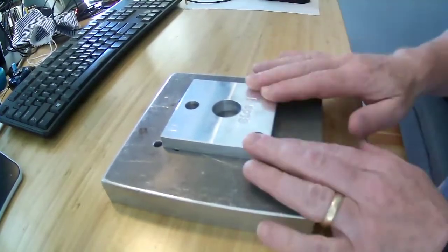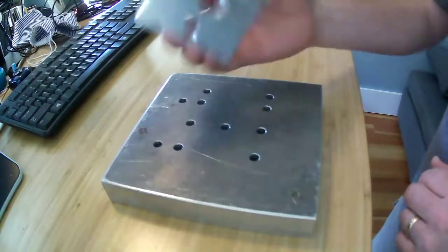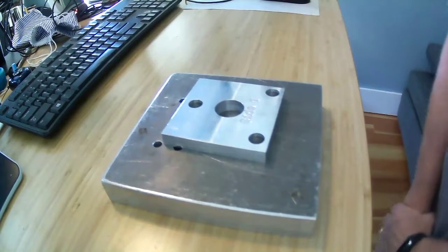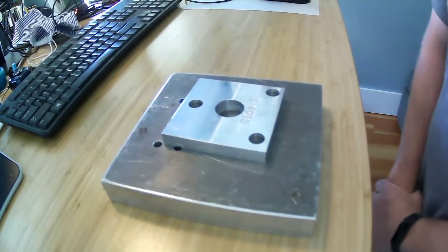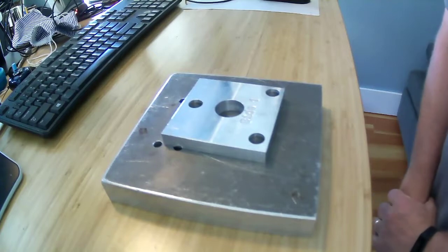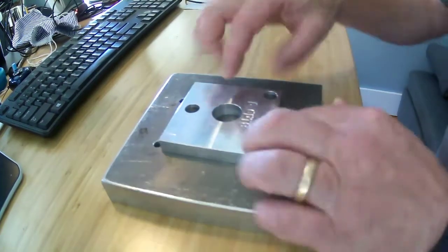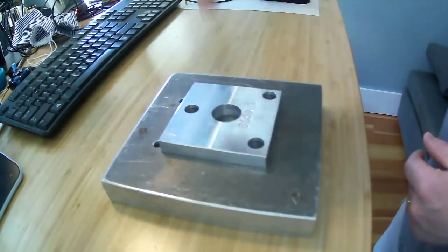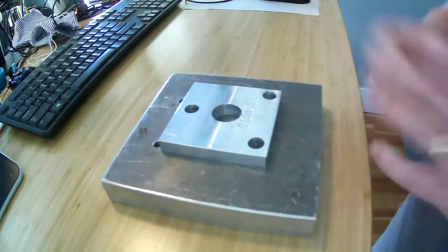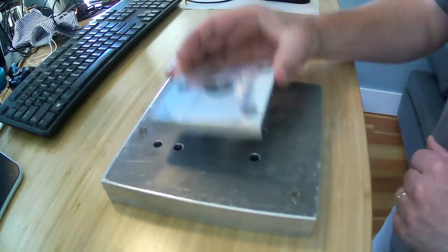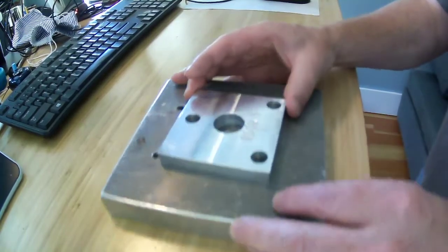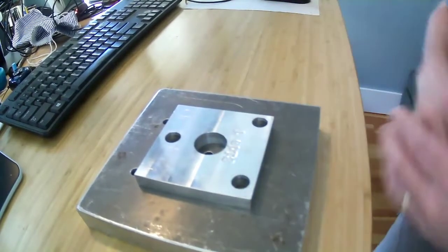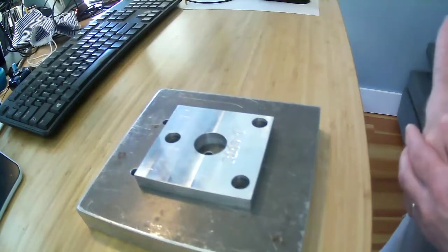All right, so if I have this plate and I want to fixture it on this big plate, I could just set it on there. And we could say, how many degrees of freedom does that remove? A plane on a plane, well, it looks like it won't move down anymore. So we've eliminated the z axis of motion. And remember, we've just eliminated it in one direction. It could still come up, but we will call it eliminated because we could always put a clamp on it, and that would hold it against this, and then we would have eliminated both up and down. So 1 degree of freedom.